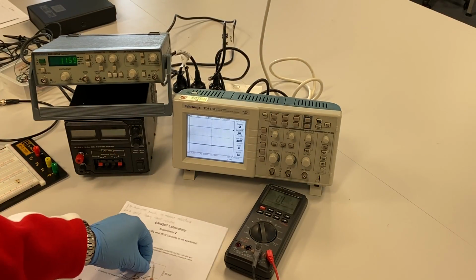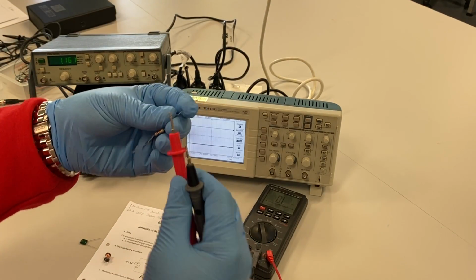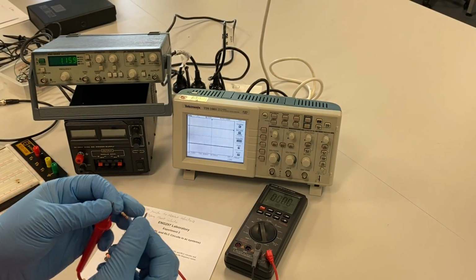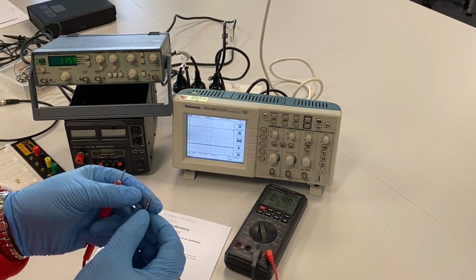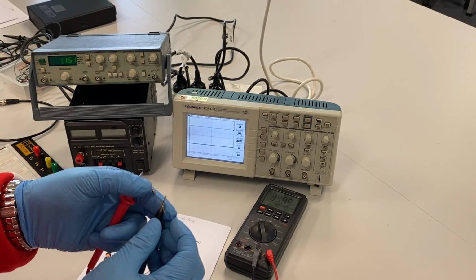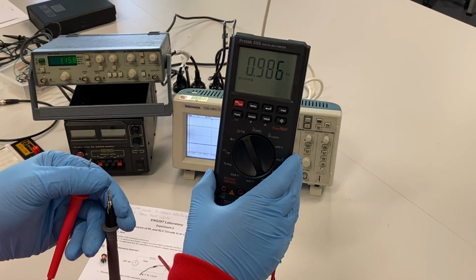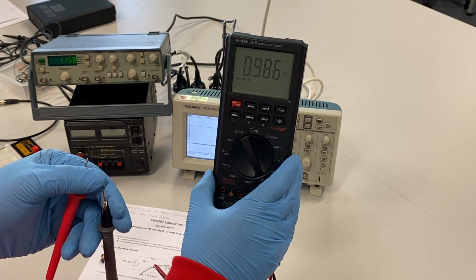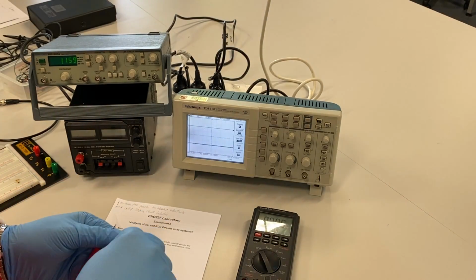What I'll do, like what I know, a resistor is just a passive circuit element, so it does not matter where I put the positive side or the negative side of these probes. Then I want to see how much resistance I will measure, right? If I put this across the probes, I want to see how much resistance. As I said, this should be a 1K resistor, right? As we can see, it's 986 ohms, 0.986 kilo. So it means this is a 1K resistor. That's correct. So I put it down.